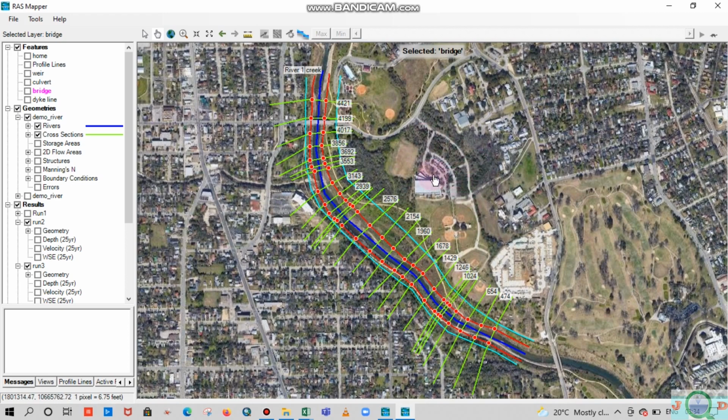If you compare the number of cross sections to the last video, where I developed a simple 1D steady flow model, the major difference you can find is that here I have added more cross sections. More cross sections because I'm going to add the hydraulic structures, and another major factor is that in an upcoming video I will develop an unsteady flow model for the same set of hydraulic structures for this river reach.